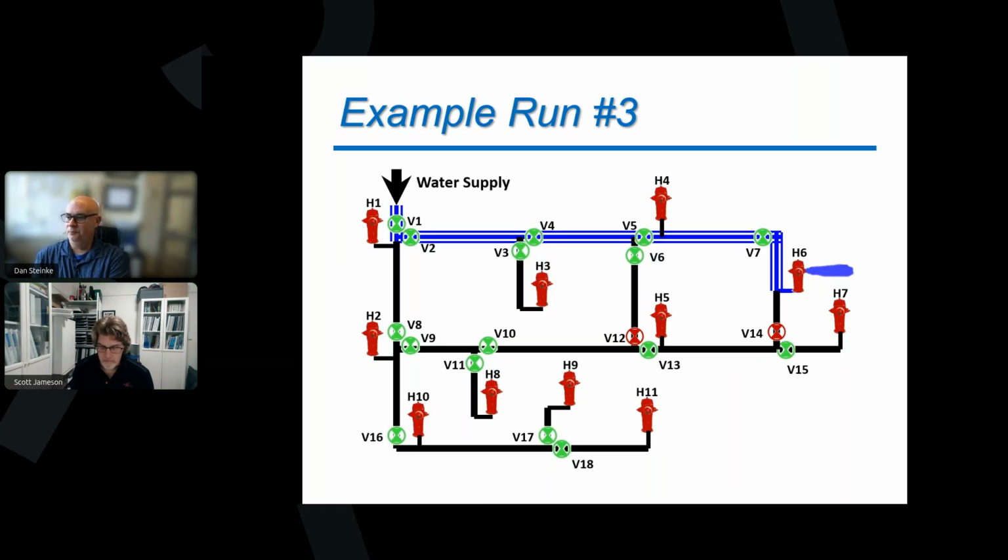All right, thank you. Kim asks, with drought precautions in place, are there changes to the number of flushes conducted per year? Yeah, so what we're seeing with that one, Kim, is changes in when people are doing flushing. Typically, we would always say we're going to do flushing in the spring. What I really see out in the field now is places changing, and they're like, you know what, we're going to do flushing in the fall now, while we've got heavy rains, and all our reservoirs are full, and we're not having huge water use in our systems.